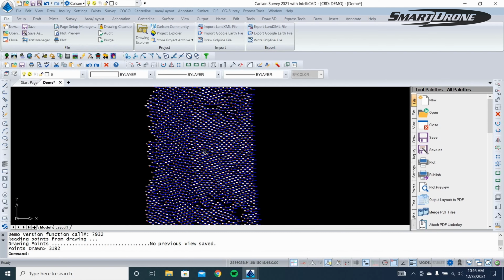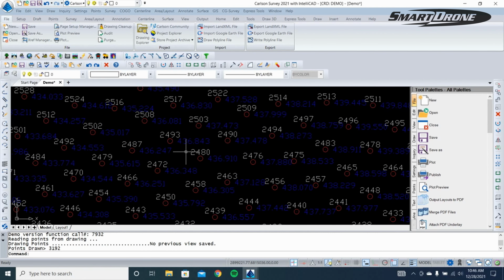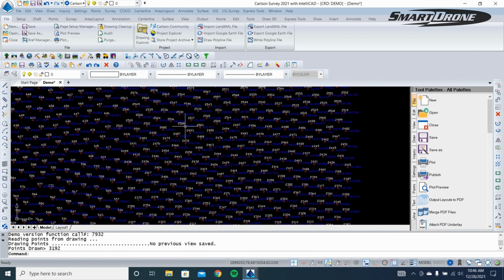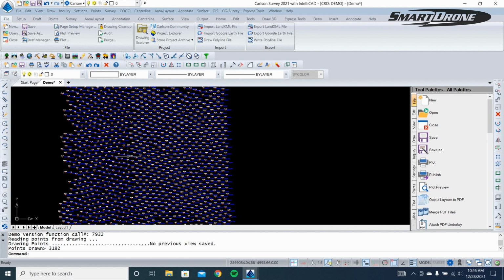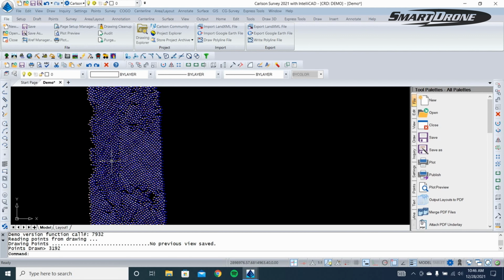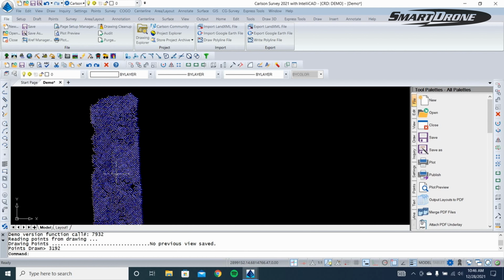And so that's how we get files like this, where we get the ground point at each one of these 25 foot grids, which is really useful. And what we've seen is that this method fits into the surveyors' and the civil engineers' method of using ENZ files or XYZ files to build surfaces.